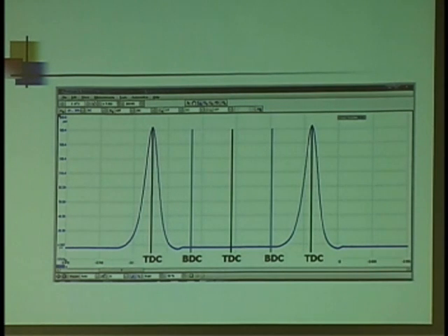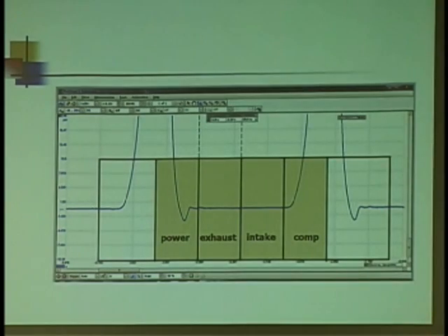Now this is not running. This is just cranking the engine over. As the piston moves back down, isn't the reverse happening? As the volume starts to increase, the pressure decreases. So if I get to the same bottom dead center as I started off with, shouldn't this line be straight? What is that little dip? Isn't that the other valve opening?